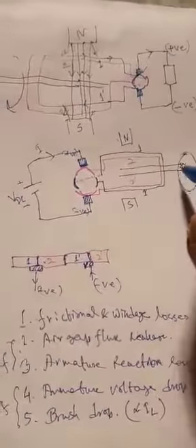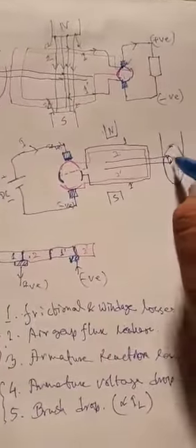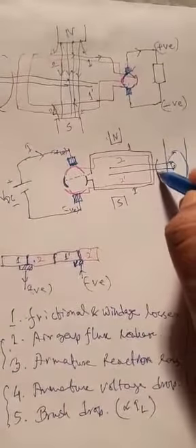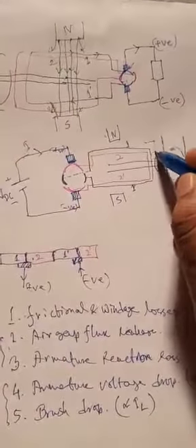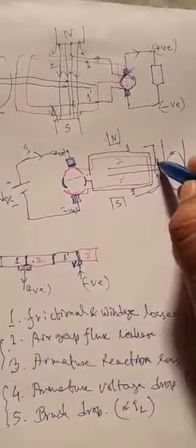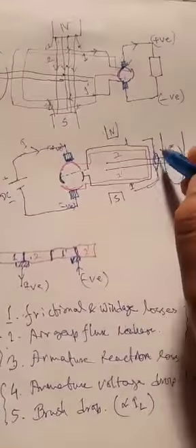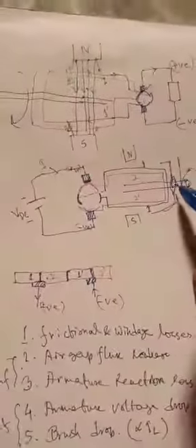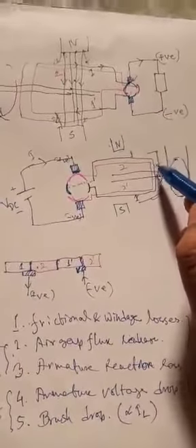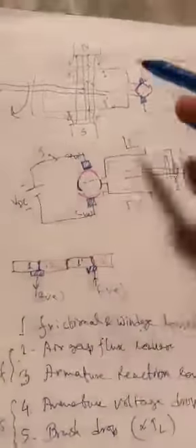If we consider it is a brake drum, it will be attached to that, and when you try to rotate this brake drum, at the very opening of the motor, where the spindle is attached with some kind of bearing, a frictional loss will happen, as well as the same kind of fan setup inside the motor for cooling, and due to that fan setup there will be windage losses also.